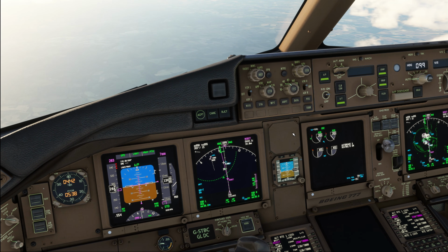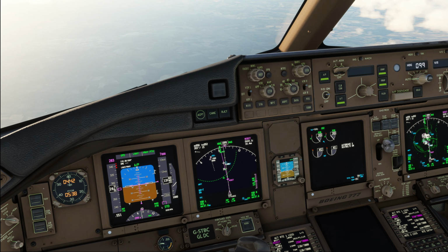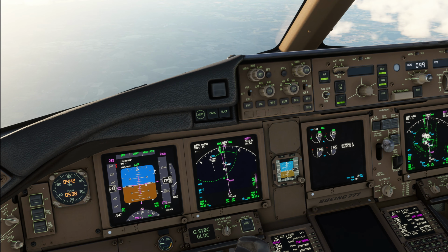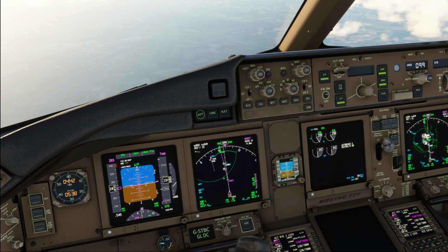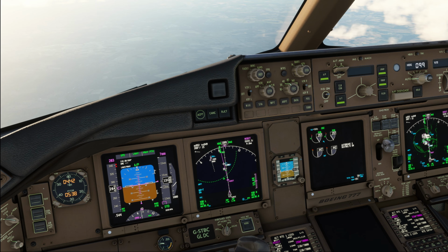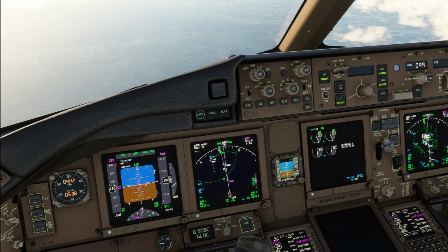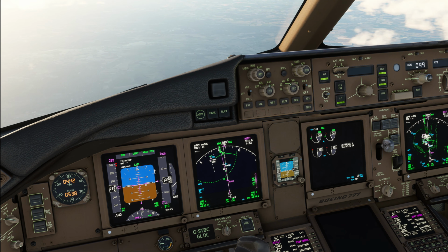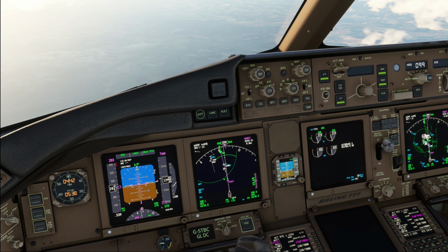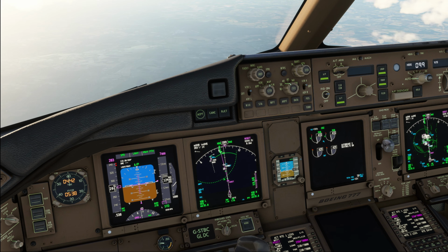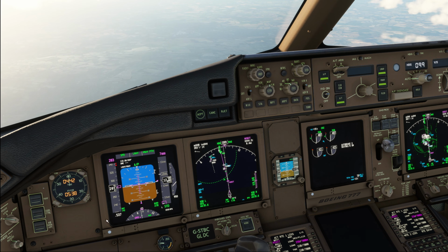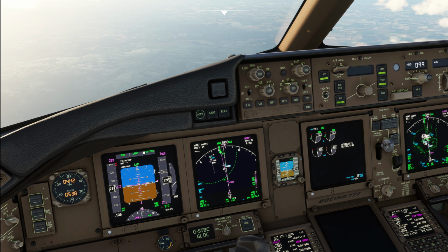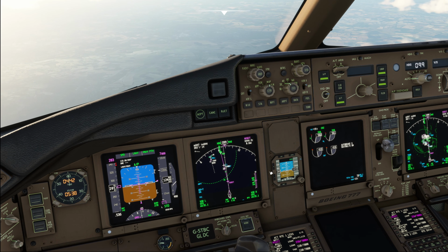There is one big gotcha in the 777 with those profiles, and that is that these profiles are based on a constant rate of descent and they do not take deceleration segments into account. In other words, when we approach flight level 100, the airplane is not going to automatically decelerate, but much rather the airplane is going to simply set the speed target down, and if it cannot slow down, it will revert to VNAV speed and thereby lose the path.